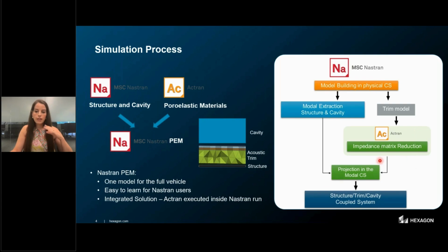So this projection over here, what it does, it just allows us to integrate the effect of the trim components into the broader dynamic analysis that we have, aligning, of course, with the dominant modes of vibration for both fluid and structure. Okay, so we add the trim contribution to the dynamic behavior of the coupled problem in a way that maintains both accuracy and computational efficiency, and of course in a way that is actually going to yield more accurate results for any dynamic analysis that we are actually doing.